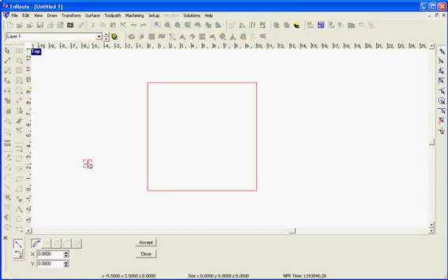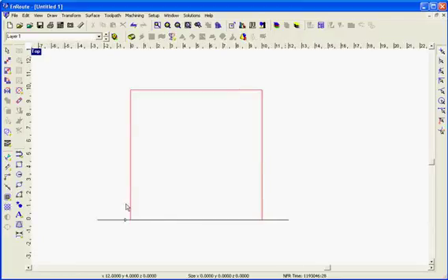And this is a little bit more restrictive than some of the other types of pieces that can be made. For starters, this part has to be made out of a straight line, and we easily created a straight line by just clicking on our screen, holding the shift key down and dragging it along the x-axis. When you create the second point, a straight line will be created. We then moved it to the bottom middle of the plate by hitting the Control and the number 2 from the number pad to the right of the keyboard.